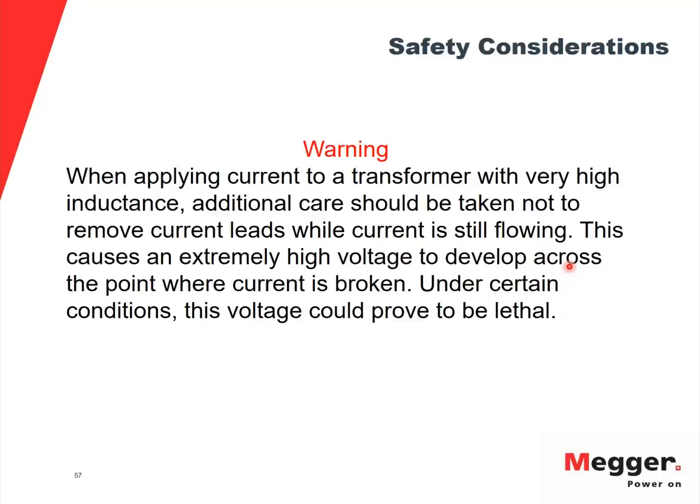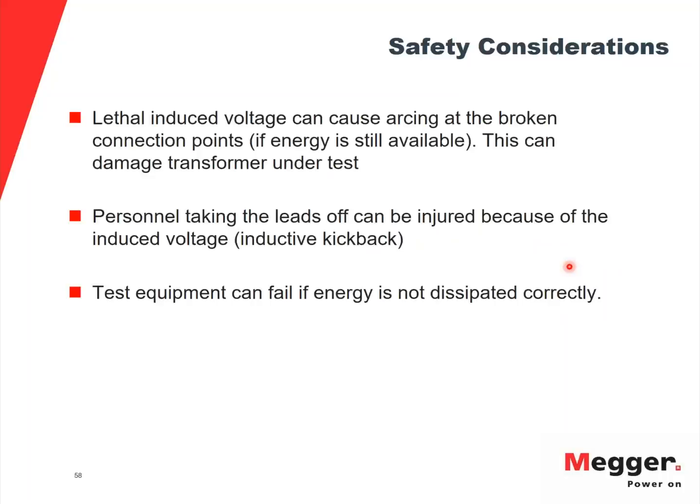So it's highly recommended to discharge the energy stored in the winding before you take the leads off. Most automated test sets do that automatically. At the end of the test, they discharge the stored energy, so that way it is safe to take the leads off.